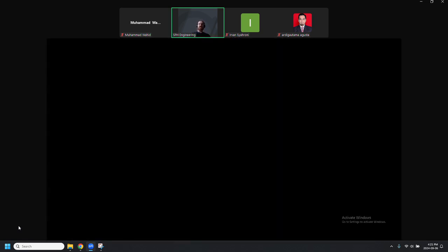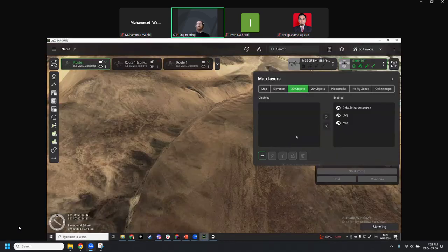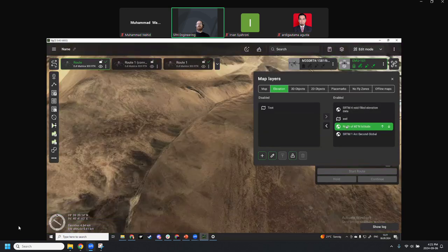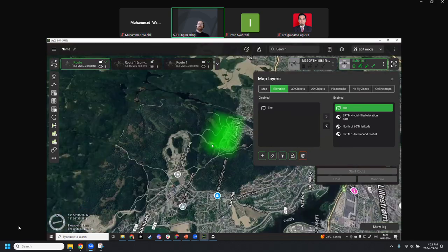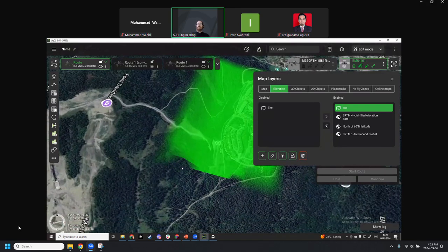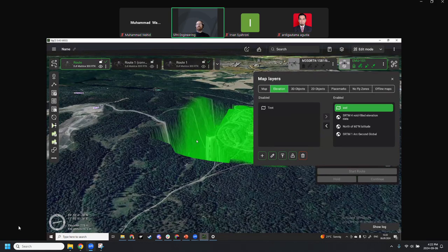If you're using any other map processing software, then please remember that these elevation sources use WGS84 with EGM96 heights. So if you don't want the same situation as this, where you have a large gap in elevation data, use EGM96 elevation, and then it will be mostly correct.